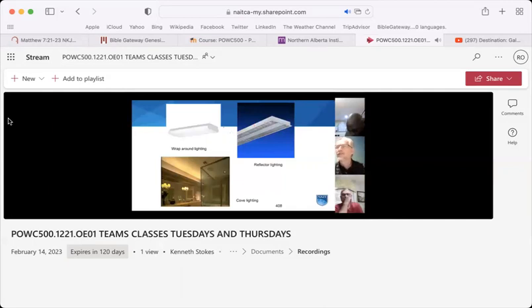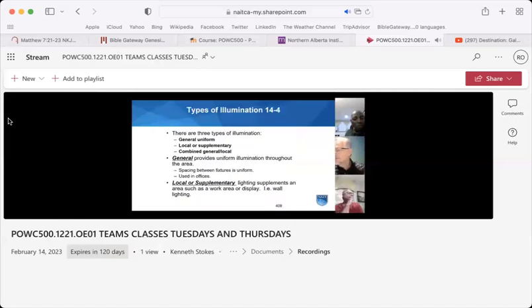So typical recessed troffer. Sometimes they're wraparound, they drop below the ceiling and they give light off the sides. Occasionally we'll see reflector type troffers. These will have more light going down and less light going off to the sides. Cove or indirect lighting will be hidden behind some architectural feature to give us a softer, more calming type of light.